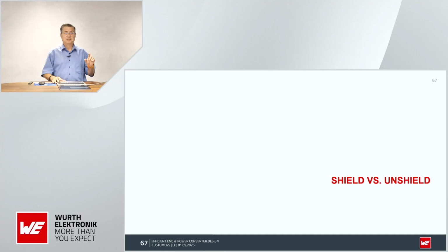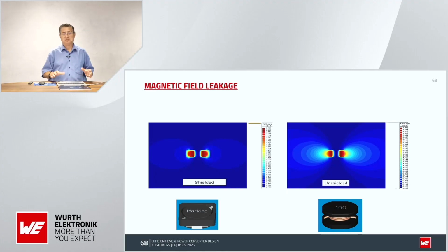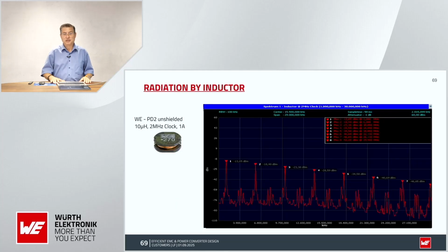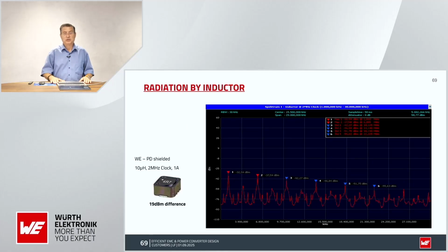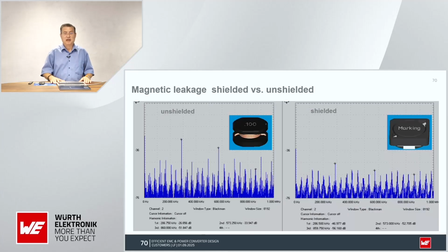Some little explanation of the benefit of shielded versus unshielded inductance. Both have a bobbin core with some wire, and the benefit is less radiation. This is a conducted emission measurement without shielding. The same DC-DC converter with shielding. I think you can see for yourself that the peaks are lower, and in the anechoic chamber it paid back in radiated emission. Always use a shielded inductor for storage, rule number 1. That's the best thing you can do if you want to avoid EMI problems.